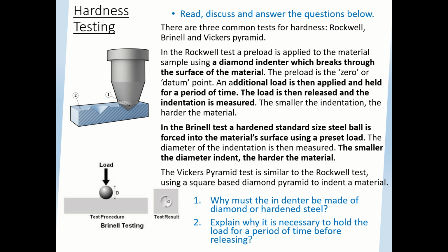And explain why it's necessary to hold the load for a period of time before releasing. It's got to hold it down so you don't get an instant spring back. The longer it's held down, the more that material has time to deform slightly.